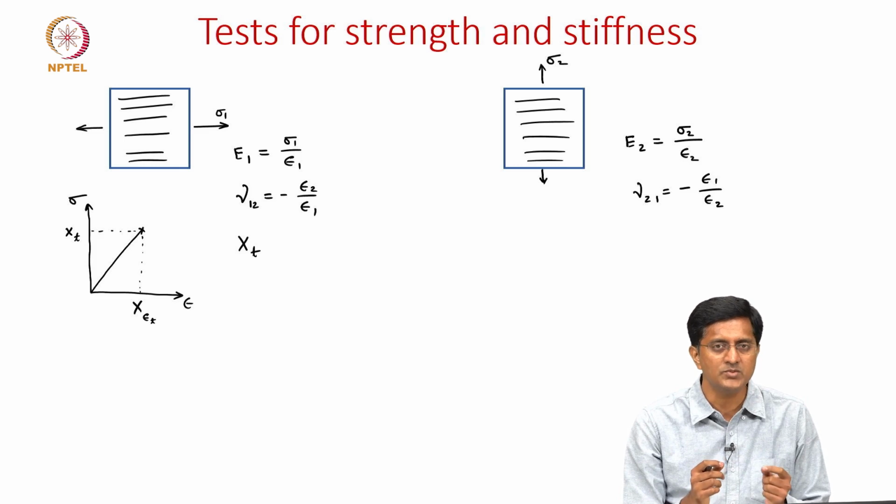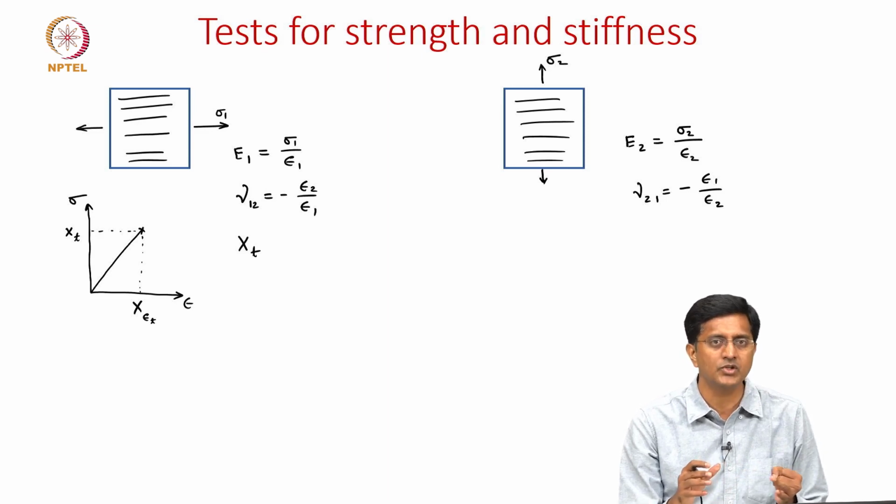But if there is a mismatch, then one should doubt the experiment, meaning the data collection might be wrong, or maybe it's also possible that the material is not linear elastic, because this relation between the Poisson ratios comes from linear elastic assumptions.